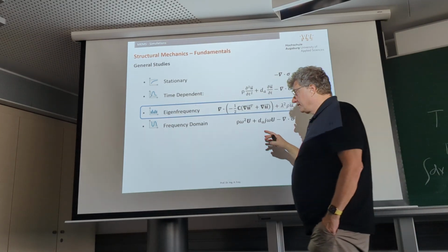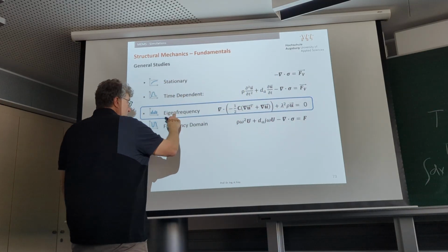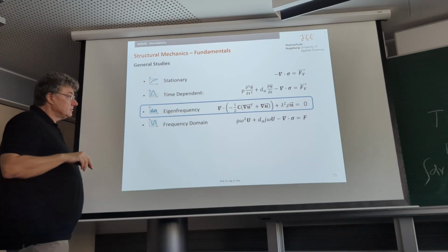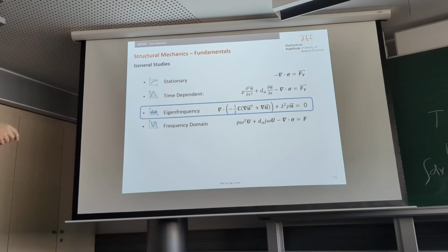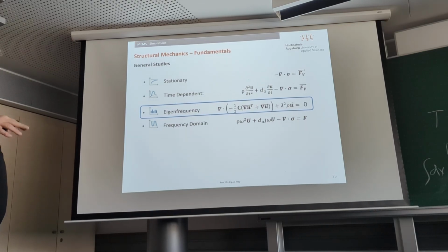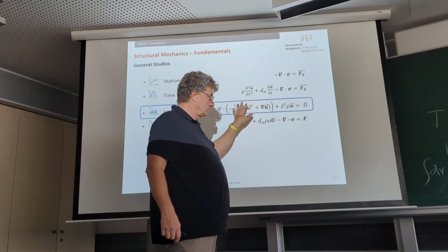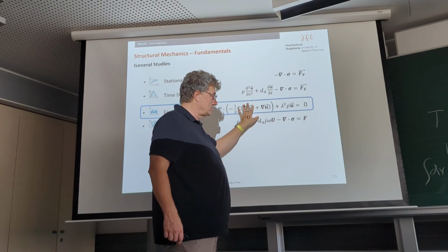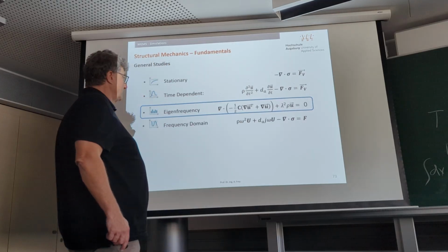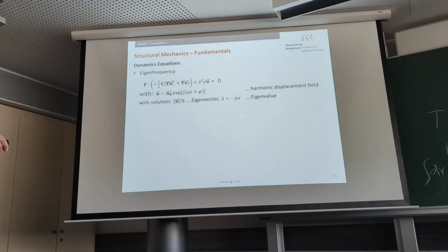One particular simulation type here is the so-called eigenfrequency simulation. So the program calculates all frequencies at which the mechanical structure is oscillating or resonating. I won't start discussing the details of that equation, but anyway, that's the equation solved, and it provides eigenvectors and eigenvalues.